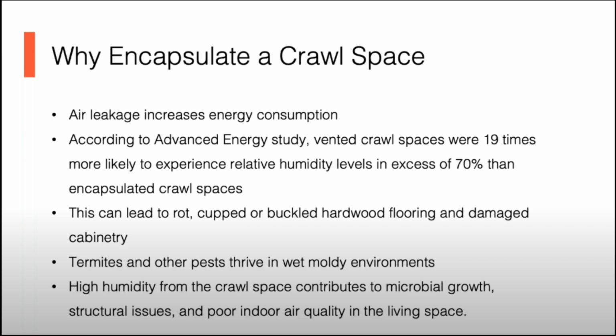According to Advanced Energy, homes with vented crawlspaces are 19 times more likely to experience high relative humidity levels in excess of 70%. This can lead to a lot of rot, cupping, and buckling of hardwood flooring, and even damage to cabinetry. Again, if it's hot and humid outside and we're bringing in that air below, we're causing a lot of damage below the home that is ultimately going to go into the house.